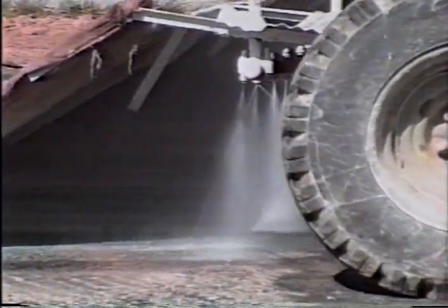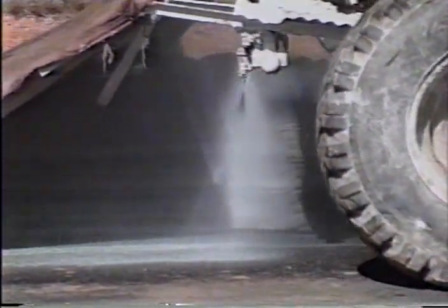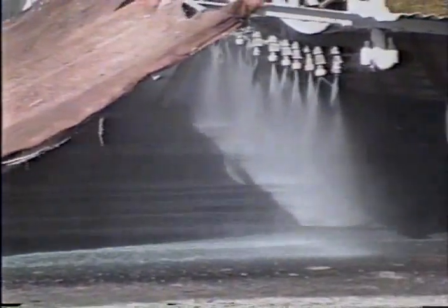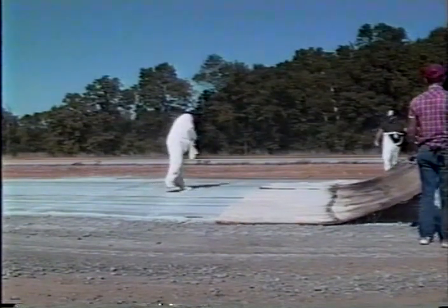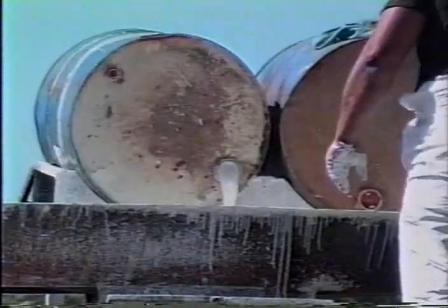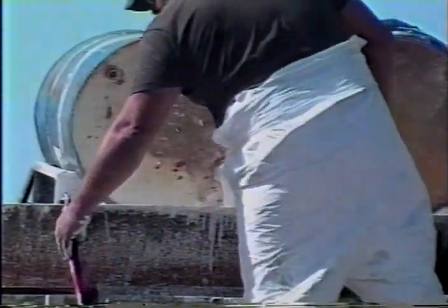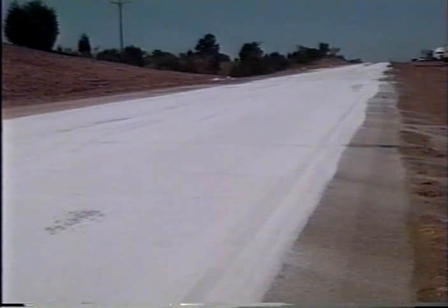During hot summer days, if asphalt concrete is being used as a separation layer, whitewash may have to be applied to prevent excessive heat buildup. Otherwise, shrinkage cracking may occur in the concrete overlay. The whitewash consists of either white pigmented curing compound or lime slurry. It can reduce surface temperature by 20 to 30 degrees Fahrenheit.